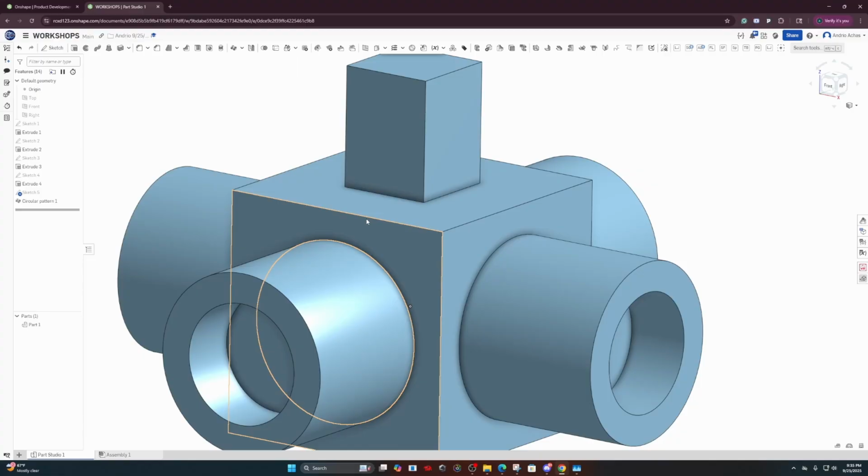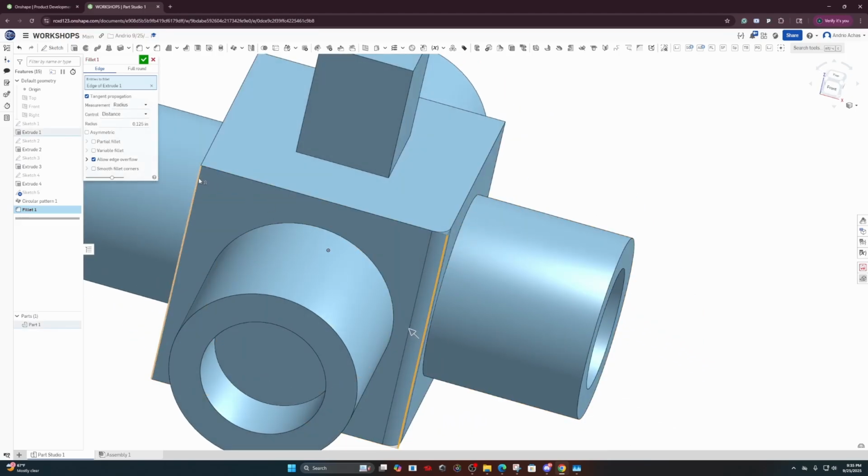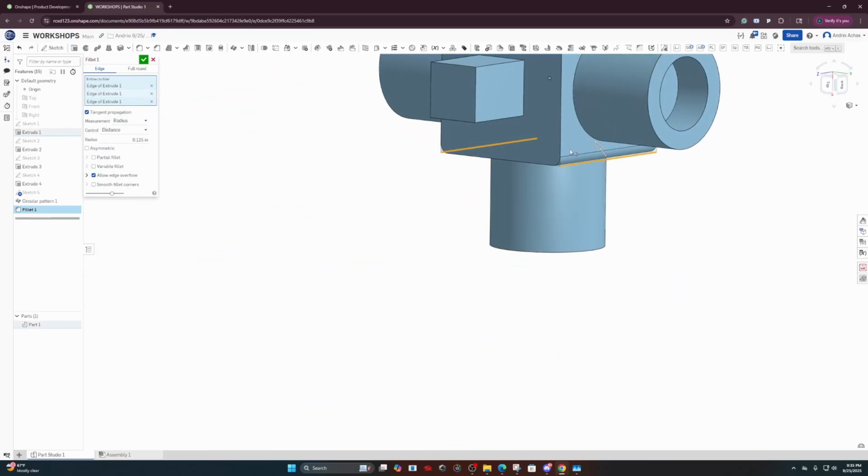The way we can get rid of these sharp edges, so let's just say when you're making a part on your own and you really don't want those sharp edges, the way we round them is using this fillet tool. Okay, that tells us what edge to find, entities to fillet. The only stuff you can fillet is faces like this. But if you want more control, select the edge. Right now we want to fillet these edges.